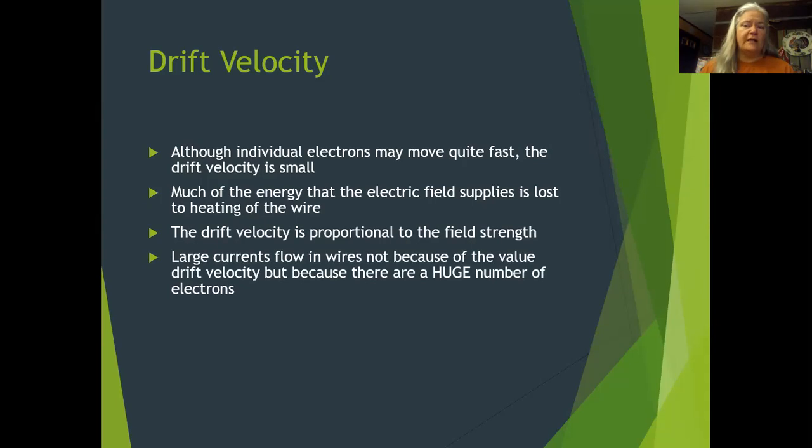So if you want to run some heavy duty electrical equipment or some large tools, you need a contractor grade extension cord, which is generally significantly more expensive because if you look at the wire inside there, it's much, much larger in diameter. We say it has a gauge difference, okay? The lower the number, the bigger the wire. So the lower the number, the larger gauge that thing has, and that will pass more current.